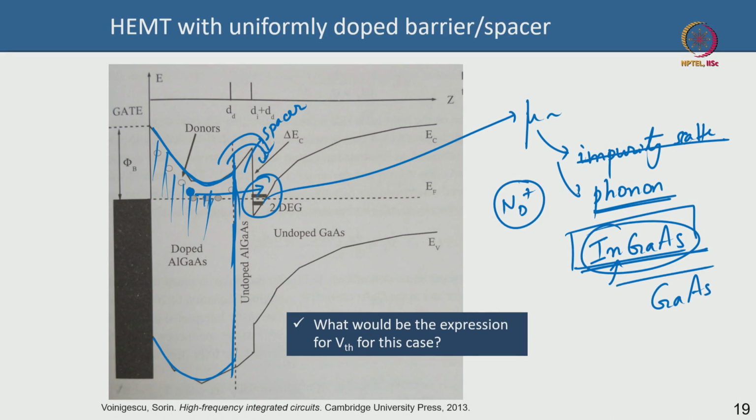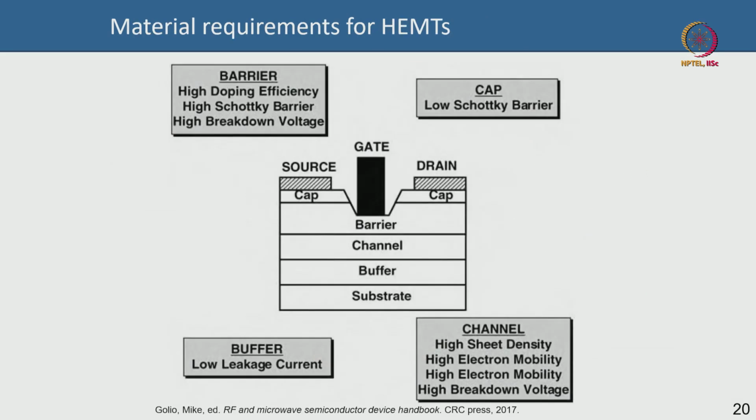We will come to that in a subsequent lecture, but here we want to talk more about the applied, technology-oriented aspect of how InGaAs HEMTs are useful, and what we need to take care of for microwave applications. If you recall your MESFET lectures, there is always at least a single recess that we have to do in a gallium arsenide FET, whether it is a MESFET or a HEMT, because the top layer will always be a highly doped N plus layer to make a good ohmic contact. That cap layer has to be etched away for the gate, because the gate cannot sit on the N plus doped cap layer, it will leak. So you have to recess it away and put the gate on the barrier.